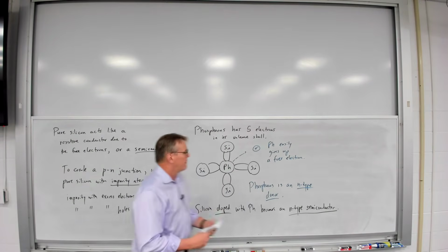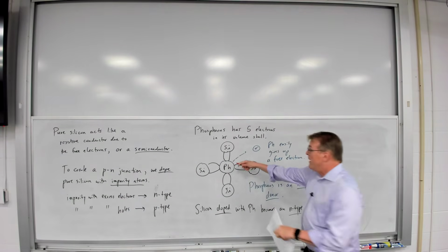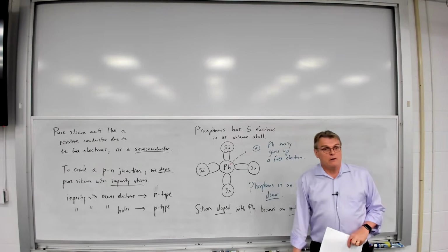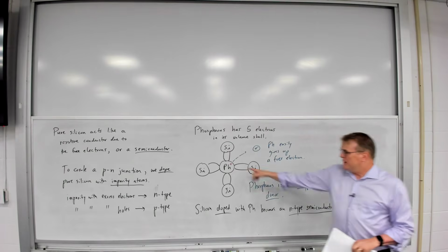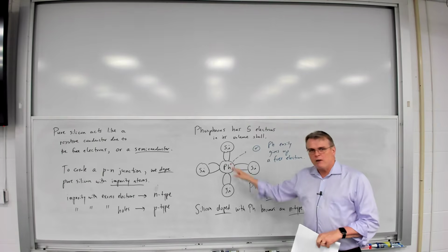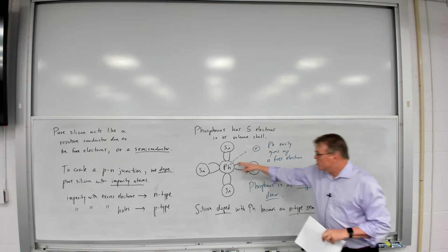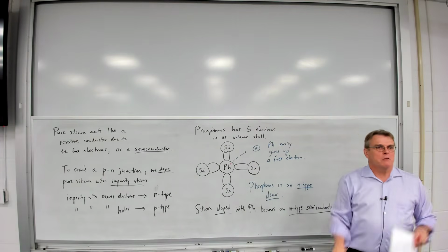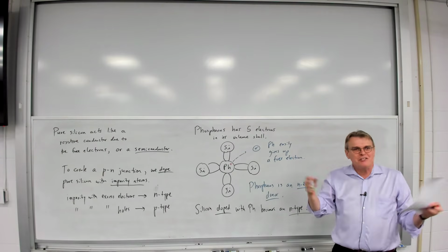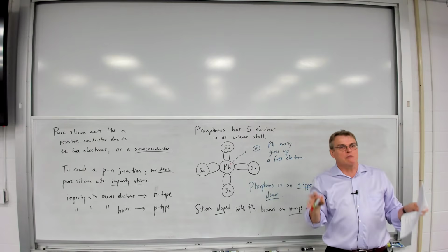All right. Now, incidentally, I also want to point out that when the phosphorus atom gives up that electron, it now has a net positive charge, right? But in this case, this is not a net charge that wants to capture an electron. Once again, that phosphorus doesn't want another electron back. But the net charge, positive plus negative, is still equal to 0. So this act of these free electrons breaking away doesn't change the fact that, electrically speaking, the entire lattice still remains electrically neutral.